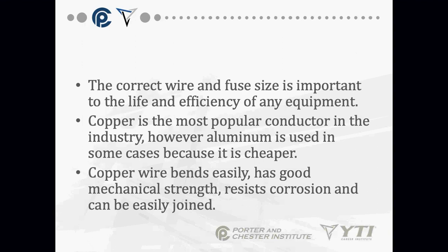We stopped using aluminum wire inside the walls of houses in the early 80s, because the aluminum wire was causing a ton of problems. If you come across a house that was wired back in the 70s, it is very possible that some of the wiring in that house is aluminum, and anytime you have to install something on aluminum wiring, that branch has to be updated.